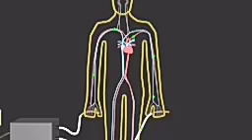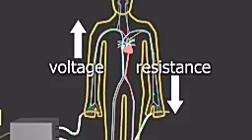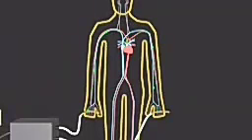When I plug in the electricity, the motor doesn't turn. That's good. That's analogous to the heart being protected by the skin resistance. The general rule is anything above 30 volts may be hazardous. But the skin resistance doesn't stay constant. The higher the voltage is, the lower the skin's resistance is. And at only around 450 to 600 volts, the skin will break down altogether and allow electricity to easily pass. It'll no longer act as much of a resistor at all.